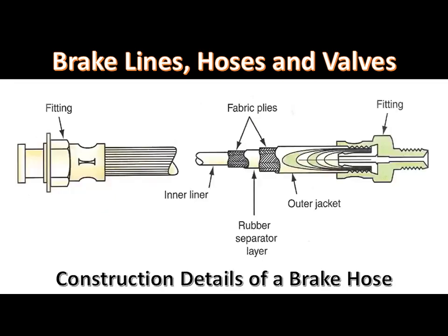Brake tubing is specially bent to fit a specific location on the vehicle. When a brake line is leaking, the complete line must be replaced, not repaired. It is preferable to replace brake lines with the OEM pre-shaped brake line.